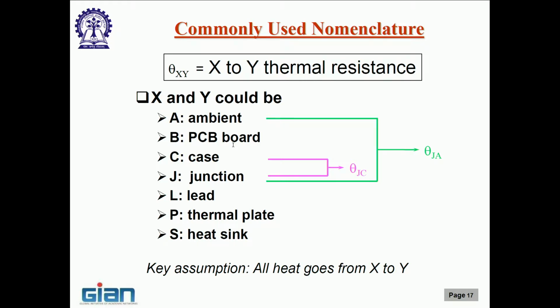Non-uniform temperature distribution is the most common, it is actually reality. You are never going to get a CPU die with the same temperature at every point. And your deciding factor for the design is the maximum temperature. It does not matter if the rest of 90% of the die is cool, but if that one point exceeds your temperature, your thermal design has failed.